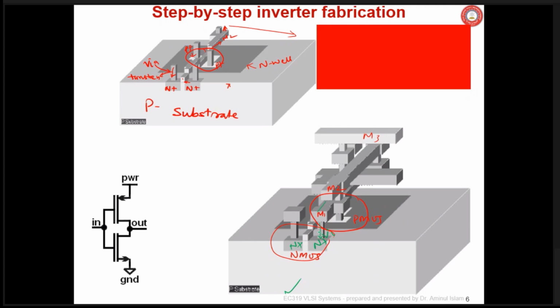Obviously this via, this hole is made through the silicon dioxide and filled, and the material is tungsten at this first via at the bottom, and other vias at the top are only aluminum, Al, and these metal lines are also mostly aluminum, metal 2, metal 3, etc.